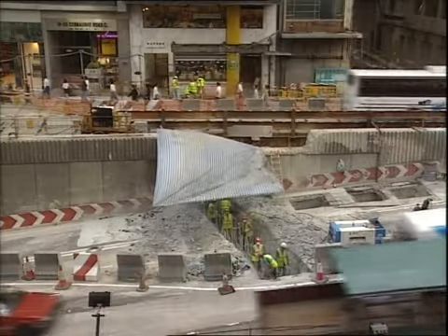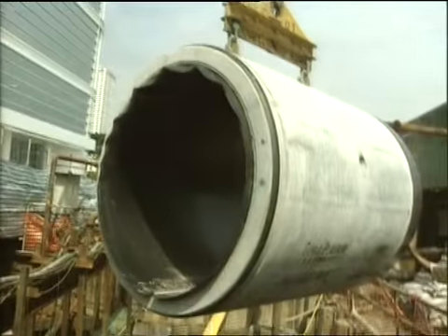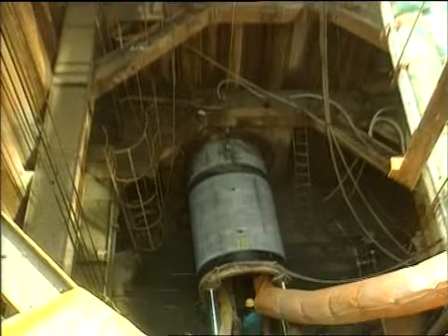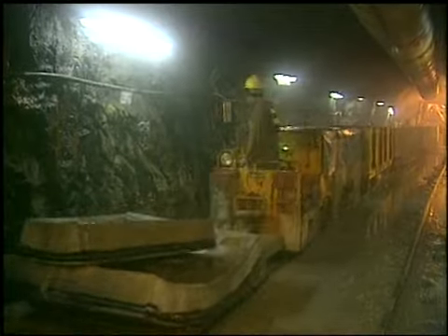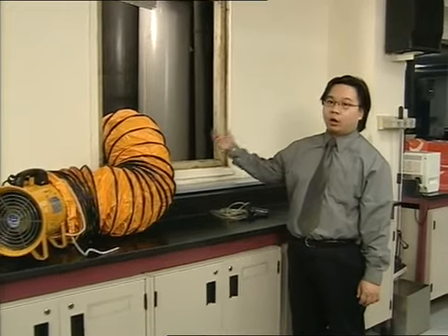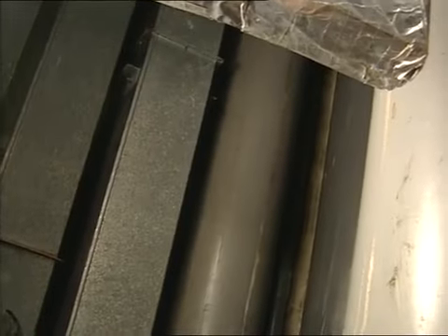However, before entering enclosed spaces to work, it is always advisable to ensure safety by checking the air's oxygen content with a measuring apparatus. Inside this enclosed room, there are many gas pipes. Before allowing workers to go in for inspection or maintenance, we have to measure the oxygen content to ensure it is safe. The process is simple.